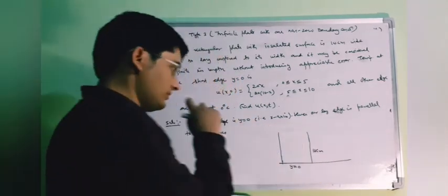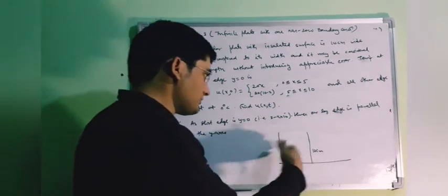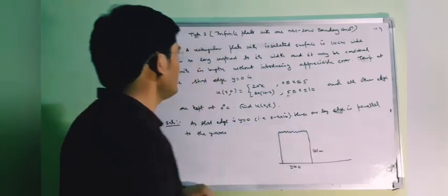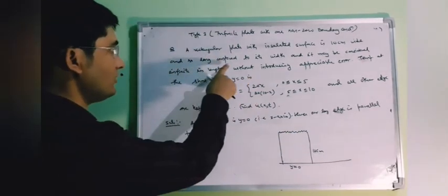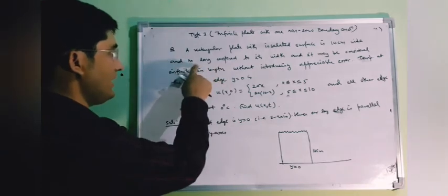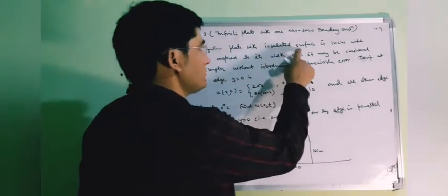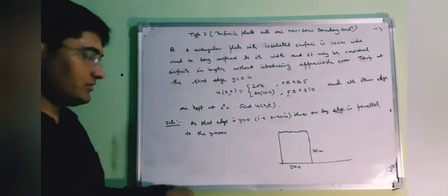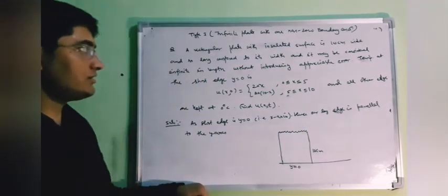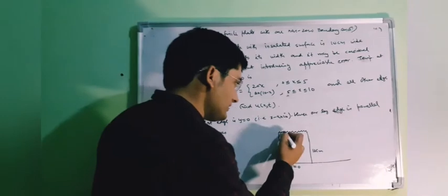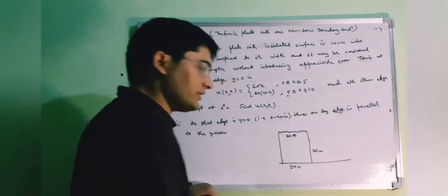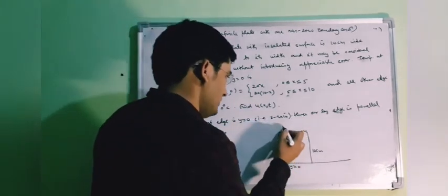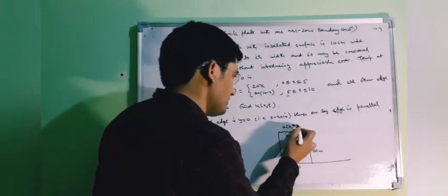And now you can see that your long edge is parallel to the y-axis, and again you can see that your rectangular plate with insulator surface is 10 centimeter wide and so long compared to its width. The length of it is very large, so we can take this one as infinite. So let us assume this one as infinite. So that means when your y is infinity, your temperature is 0.